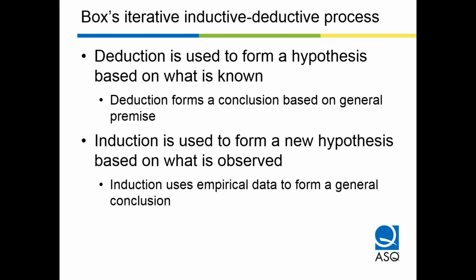And of course, be sure to control your variables. I find it's an international hobby of engineers around the world. Okay, so it could be option A, B, C, or D. Let's change everything at once and see what happens. And I'm not talking about design of experiments. I'm talking about we just changed everything, tested it, and then said, we were right, it worked. Yes, but which one? Don't change all your variables at once outside of a DOE.